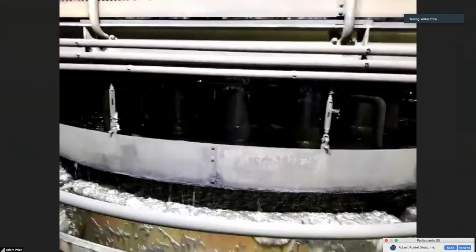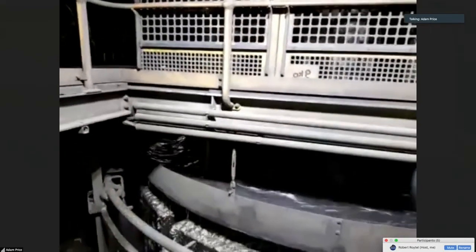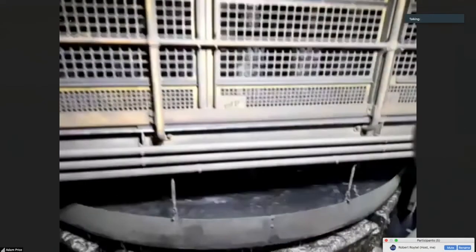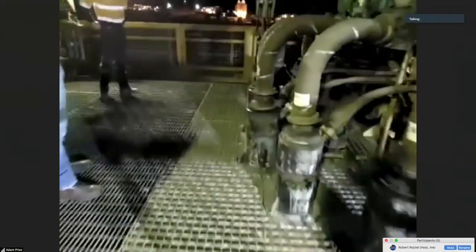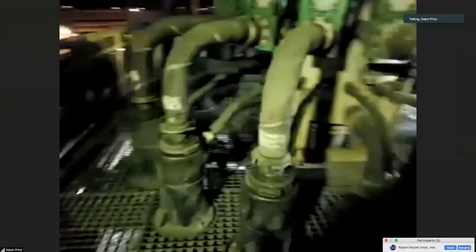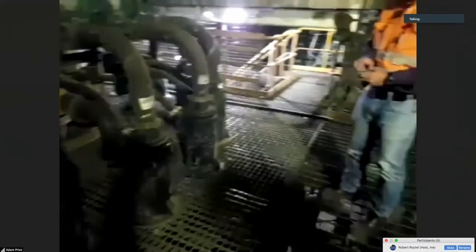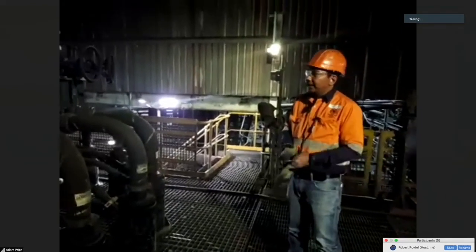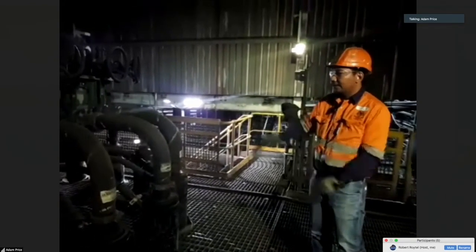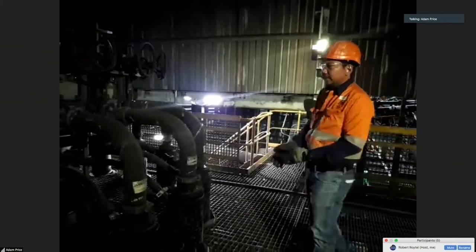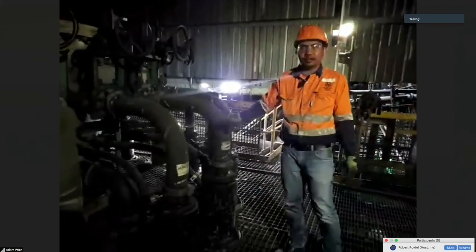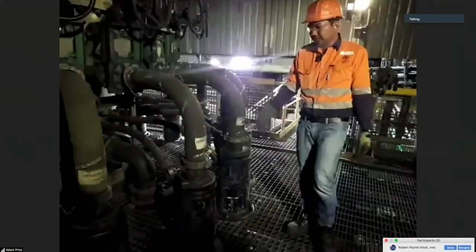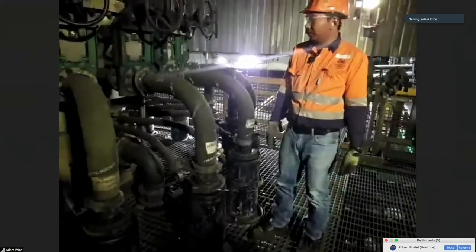So the main thing for achieving a stable operation of the Jameson cells is maintaining the downcomer pressure. This is easily achieved by using the ERM mechanism. The ERM mechanism makes sure that we have a constant level in the pump box, which feeds the recirculation pump, and at the same time feeds the downcomer distributor. Also, it's an important factor to make sure all these downcomers are not blocked. It's very easy to identify if they're blocked anyway.